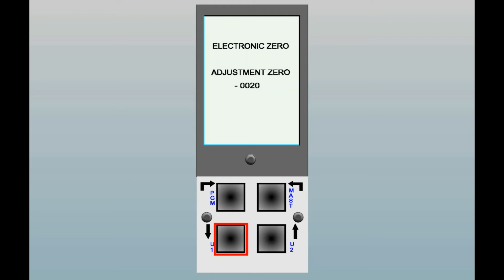If you hold the button in for more than 3 seconds, the values will change by tens, allowing for quicker movement in the setting. Ideally, you want to operate the column with these values somewhere close to the zero positions. This will give the auto mastering function the greatest amount of room to move during the mastering process. In other words, you don't want to operate with the gain at plus 1800 if you can avoid it. Whenever you're doing a recalibration involving moving the pneumatic spread or zero controls on the front panel, you should first set both of the electronic controls to their mid positions.